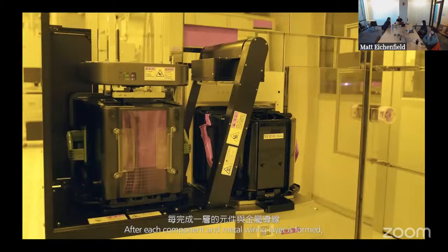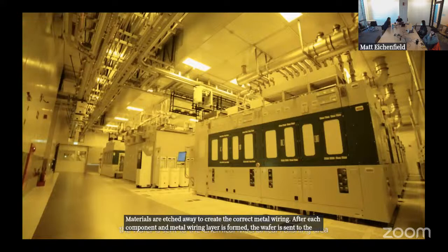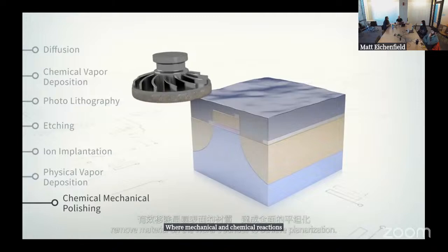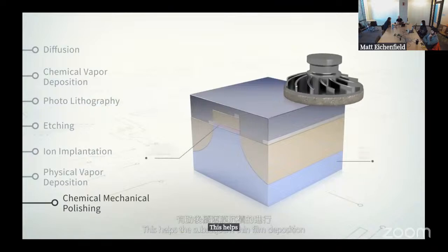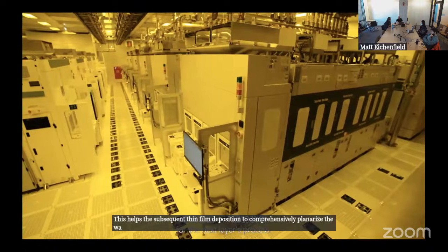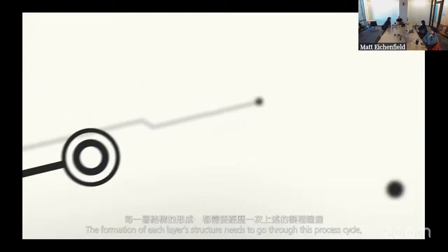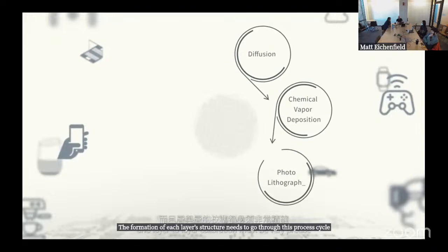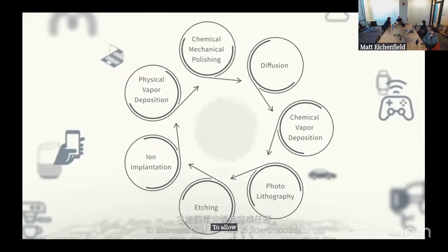After each component and metal wiring layer is formed, the wafer is sent to the chemical mechanical polishing area, where mechanical and chemical reactions remove material on the wafer's surface to achieve planarization. This helps the subsequent thin film deposition to comprehensively planarize the wafer's surface for the next layer's process. The formation of each layer's structure needs to go through this process cycle, and layer-to-layer calibration must be very precise to allow electrical currents to flow smoothly.